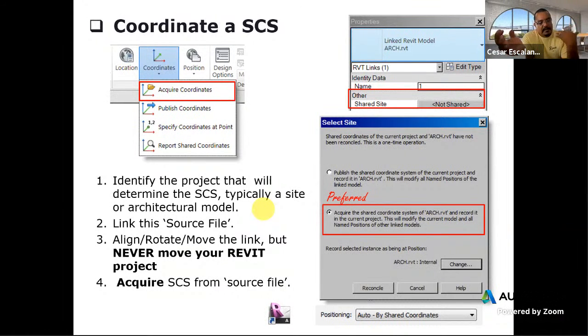And you've seen these typical monuments in the cities. They are usually these metal plates sitting at the sidewalks or street intersections that are registered with the state of California. If you're working in California, if you walk down San Francisco, you find them everywhere. And those points are usually monuments that are used by the civil surveyor to anchor the survey elevations of existing conditions.